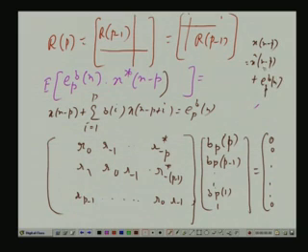This x cap n minus p is its prediction, a linear combination of the p future values, that is orthogonal to E p b n. So, that product will go as 0. So, what you get is nothing but E of mod E p b n square, that is the variance of the backward prediction error for pth order.